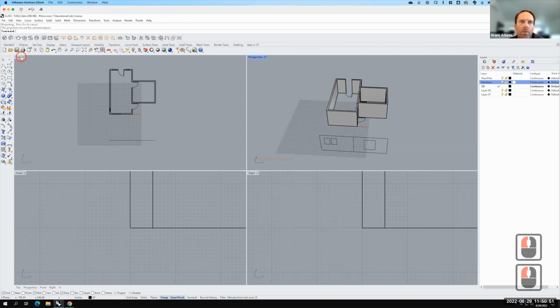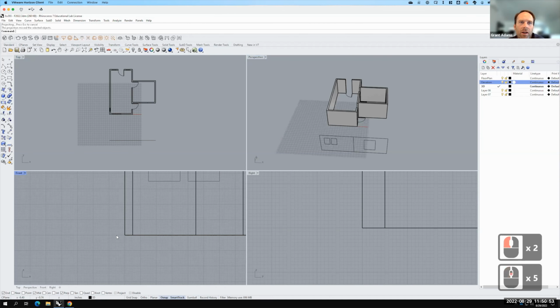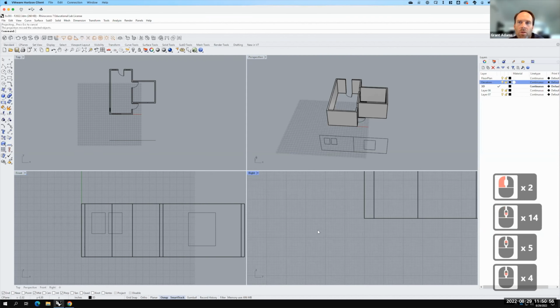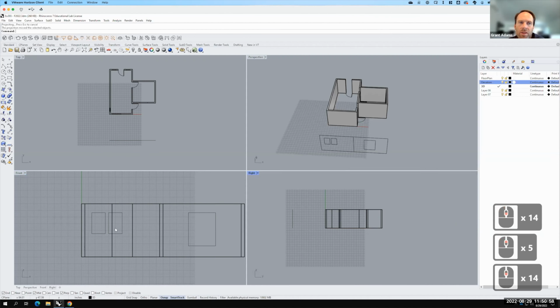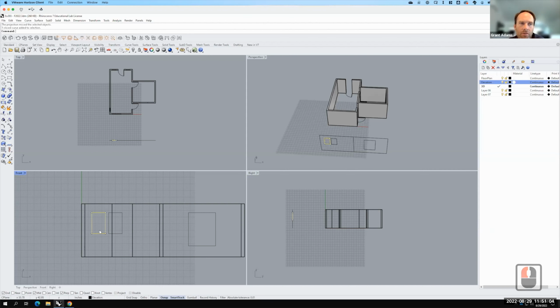So I'm going to double click on perspective, and I'm going to look down here at either the front view or the right side view. In this case, my rectangle is most visible in the front view, and I'm now going to project it from this front view straight till it hits here. So I'll leave all 4 views up so you can see it, but my front view is active, and I've selected the object in the front view.